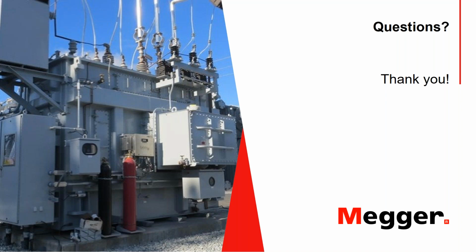We use alternating quantities. So if you do not demagnetize, what will happen is when you're performing other consequent testing, let's say the best example is excitation current, you will get values that will be erroneous because you are not magnetizing the transformer from the proper starting point, and you already have some remnants in the transformer core, and this will affect your readings.